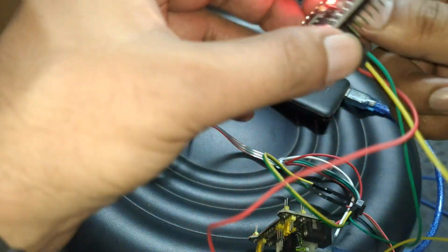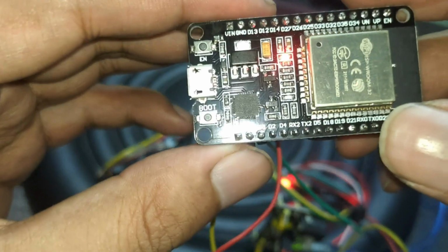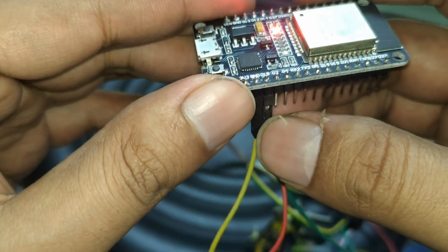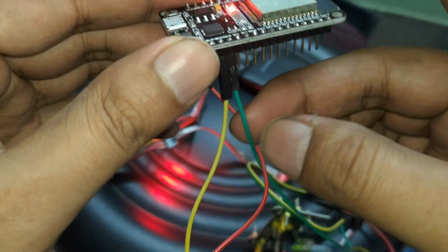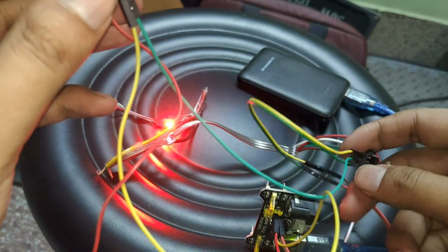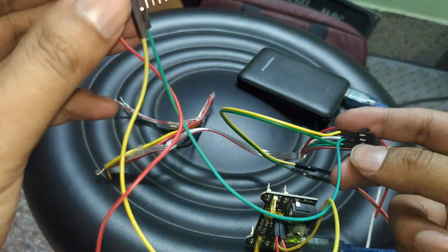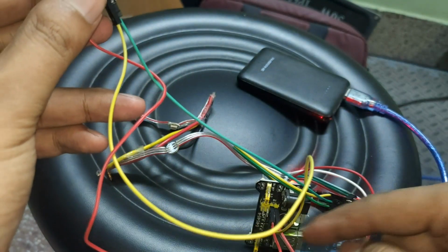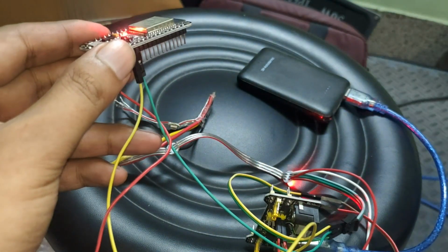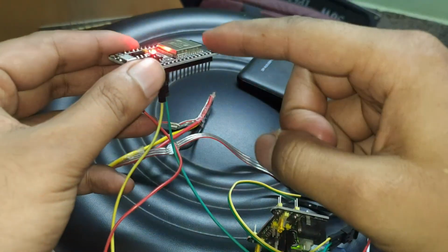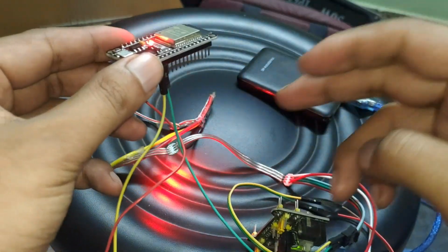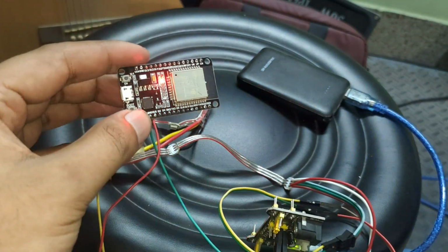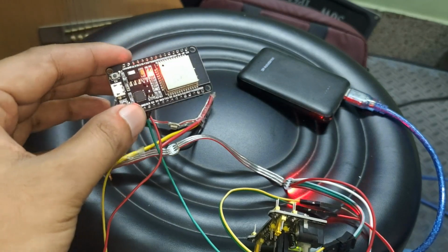So let's just see what the ESP32 has. As you can see, this is D15. I'm connecting this with this input. This is green, which is going to the LEDs. Okay, and then another one is ground. You need to connect ground to the power supply so that the whole circuit becomes workable, and whenever you produce any digital inputs, it will go through the LEDs which are connected to the board. Next part we will see the simple program which is controlling this.